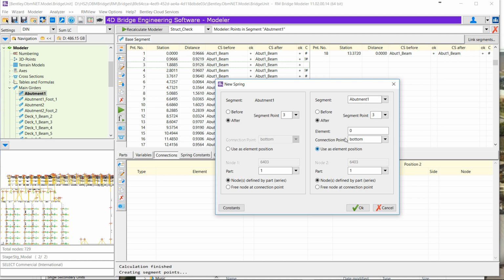So I indicate a spring representing the bearing. I will give a number, so I use from 11, so here I will use 1, 2, 3, 4, and I put the spring on one of the attachment points, whatever I want, where the spring will be represented.